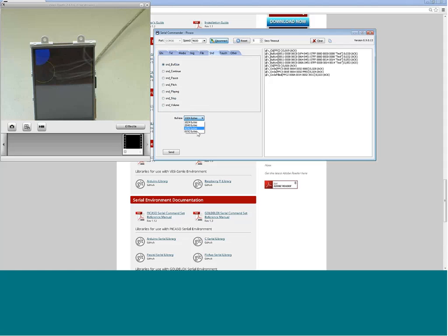So here you can define the buffer size. You have some touch options like touch detect region. If you don't want to detect the whole screen, you can specify the region where you want to detect touches, for a specific x1, x2, y1 and y2, so a specific area on the screen. And you can poll if there was a touch. And you have other functions like pin low, pin read, as shown before.